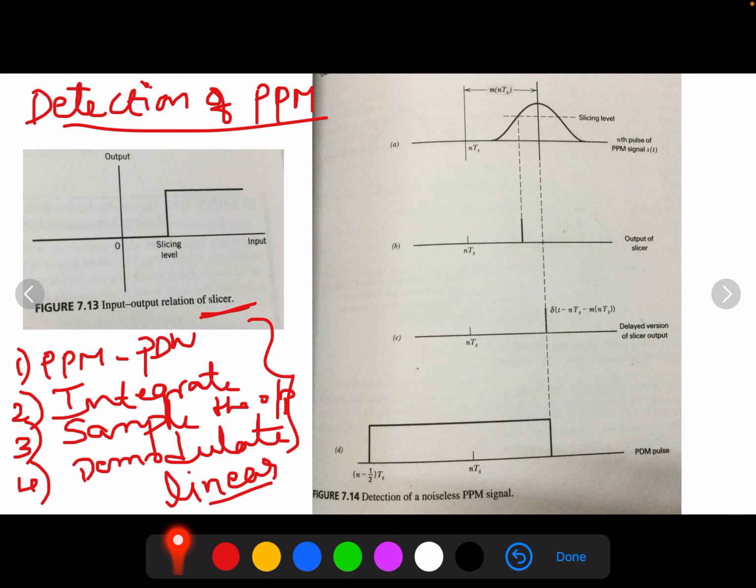The presence of additive noise affects the performance of such a system by falsifying the time at which the modulated pulses are judged to occur. Immunity to noise will be established by making the pulse build up so rapidly that the time interval during which noise can exert any perturbation is very short.